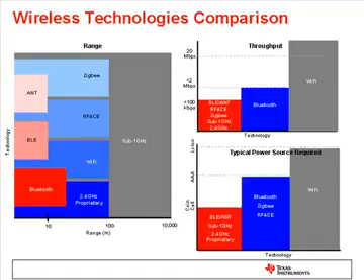From a range perspective, Bluetooth, you'll find, can go about 10 to 30 meters, depending on the application and the environment. ANT technology, Bluetooth Low Energy, go about 10 meters. 10 meters in a real-world application would be about a room's range of length. You can see that compared to Wi-Fi or Zigbee, which can go about 100 meters, which would be a house range, for example. And then sub-1 gigahertz technologies can go much further. These will vary, of course, if you have a power amplifier. You can increase your range significantly.